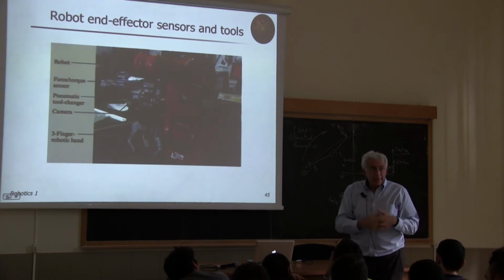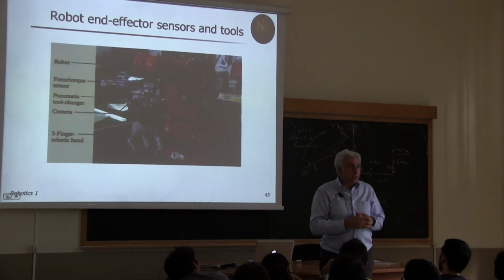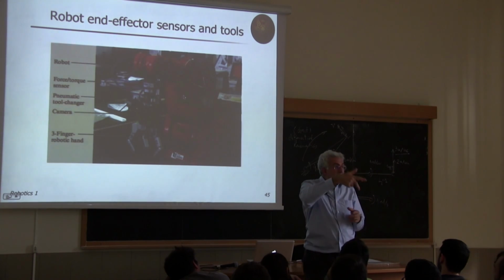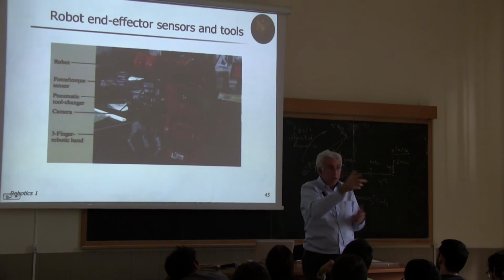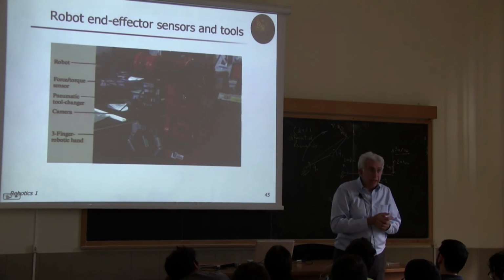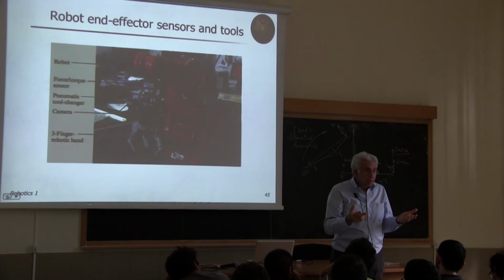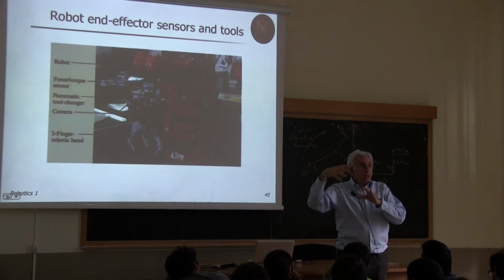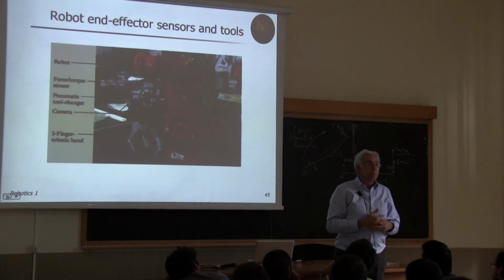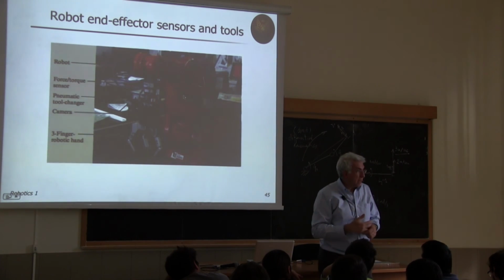And we should be able to compute the kinematic transformation associated to this, because the camera carries a known reference frame with one axis along the image axis of the camera, of the lens itself, and whatever I see with respect to the world depends on how I'm positioning and orienting the camera with the robot.